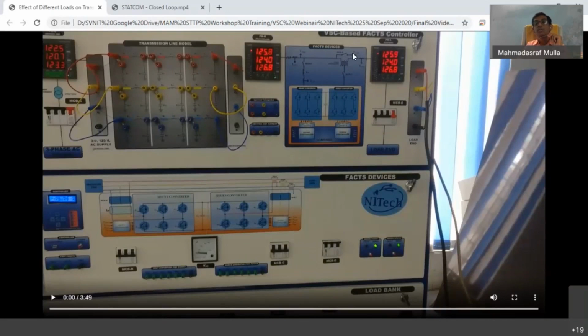And when we require UPFC operation where both shunt and series compensators are required, then this bypass MCB must be off for series. So this will connect the transformer and then both these MCBs will be on. So that is how via these 3 MCBs we can create all 3 experiments: shunt compensator, series compensator and shunt-series, that is the UPFC compensator.